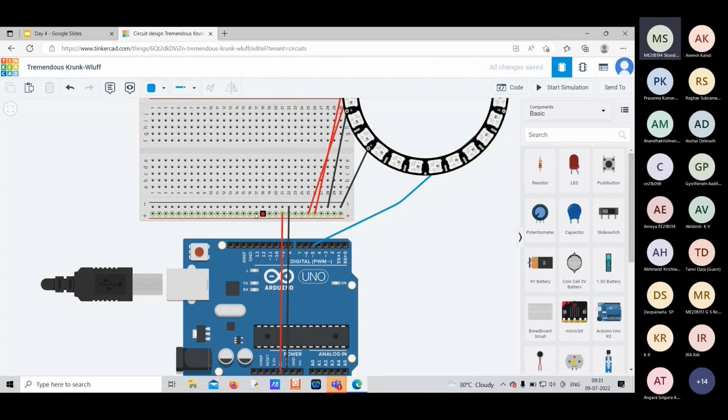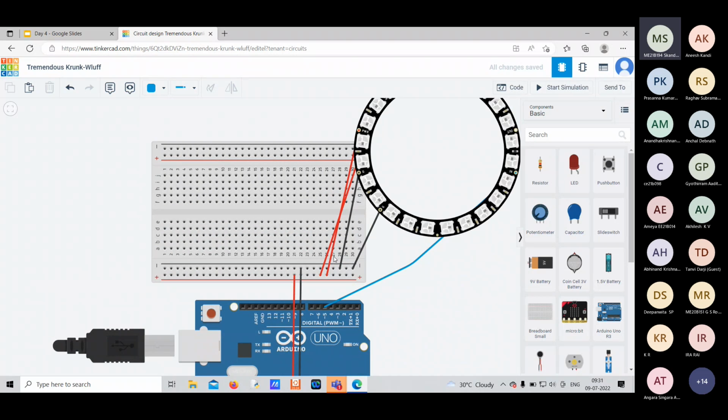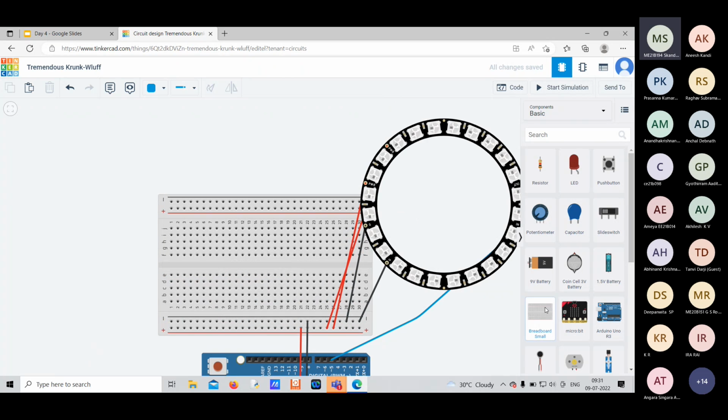Thereby, we'll have these set of pins at a very high potential, as in 5 volts, and the negative set of interconnected connections at zero potential. And then I connected those zero potential to ground of the NeoPixel and the high potential to the power pins of the NeoPixel.